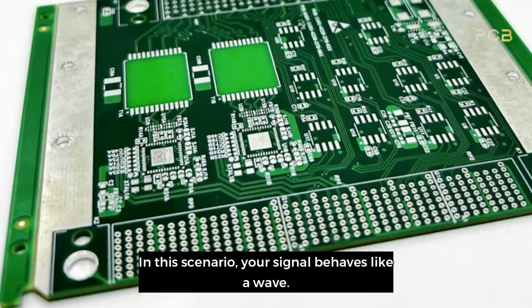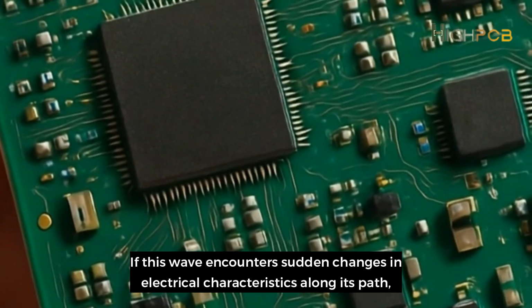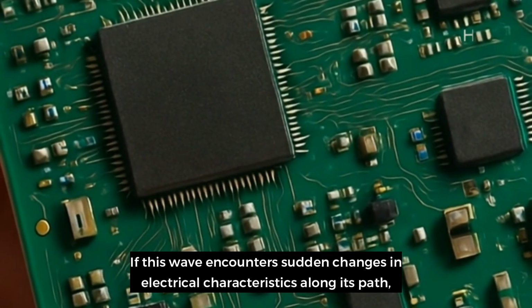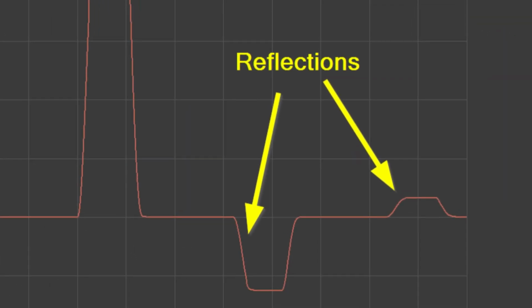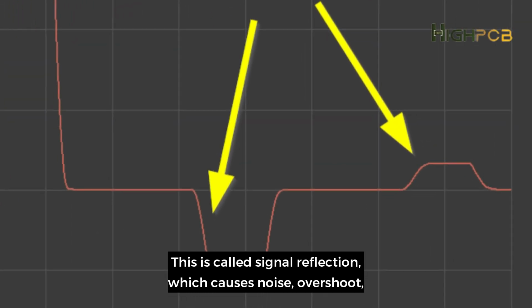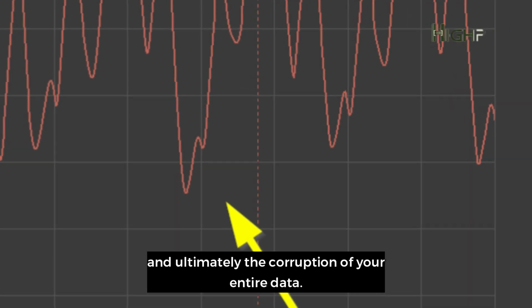In this scenario, your signal behaves like a wave. If this wave encounters sudden changes in electrical characteristics along its path, a portion of its energy reflects back toward the source. This is called signal reflection, which causes noise, overshoot, and ultimately the corruption of your entire data.